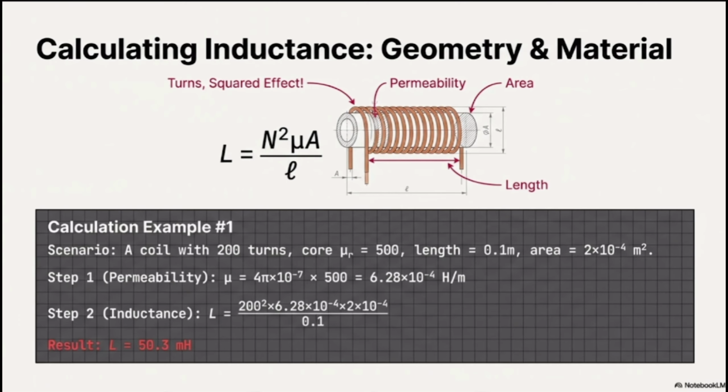As we had the formula related to the capacitor, obviously we have a formula for that. The amount of inductance, L, which we know as Henry, is going to be N to the power 2. N means the number of turns that you have for your coil, to the power 2, times mu, which we know as permeability.